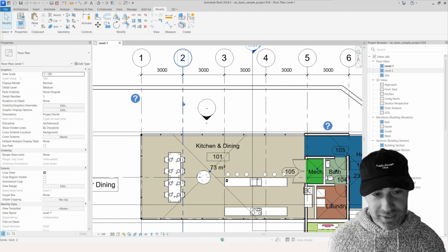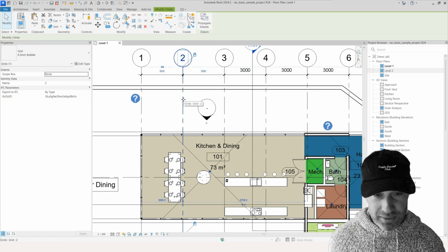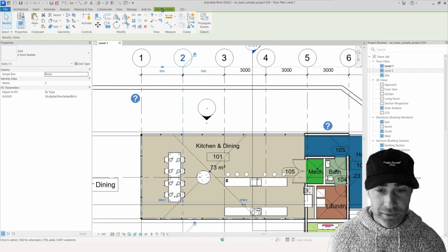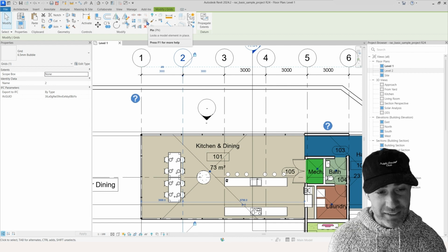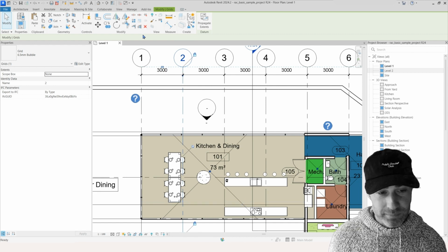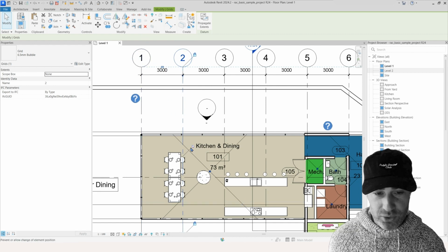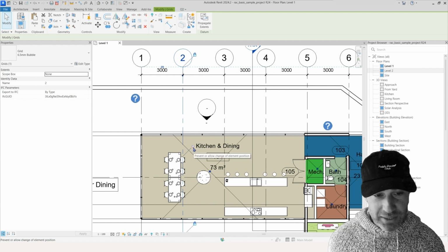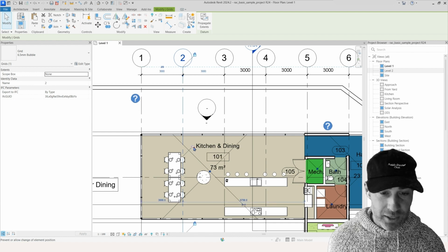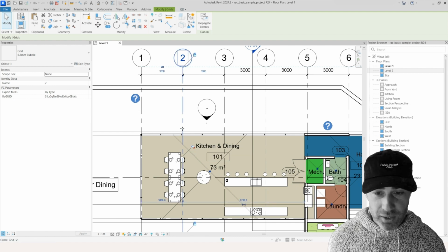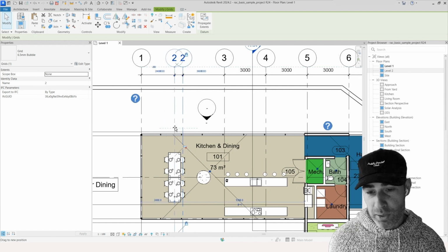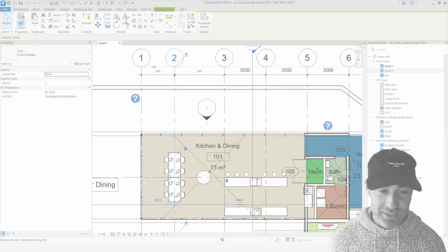do as such. Select the element itself to be pinned. Click on the Modify tab. Under the Element tab, Modify panel, click on the pin icon. Revit displays a push pin control near the element to indicate that it is pinned in place. To move or delete an element, you first must unlock it by clicking on the push pin control. Click on the push pin again to lock the element.